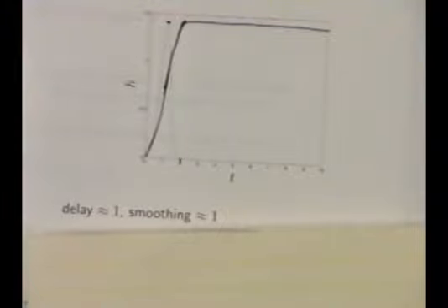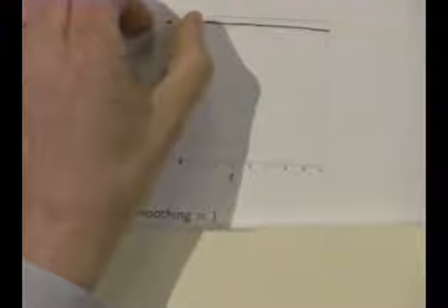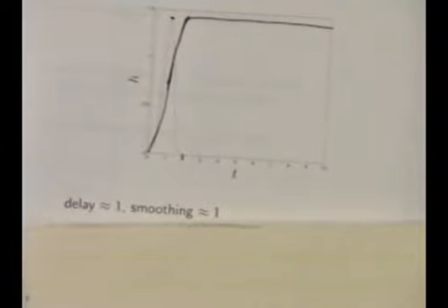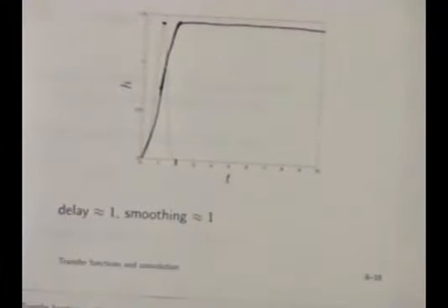You can also see that smoothing has occurred, because you put in something with an abrupt transition in voltage, and what came out had a transition that went over a period of 2 seconds. Everybody see this? Now conversely, if someone draws you a step response, you need to be able to differentiate that in your head, instantly, visually, and then talk about what that thing does.